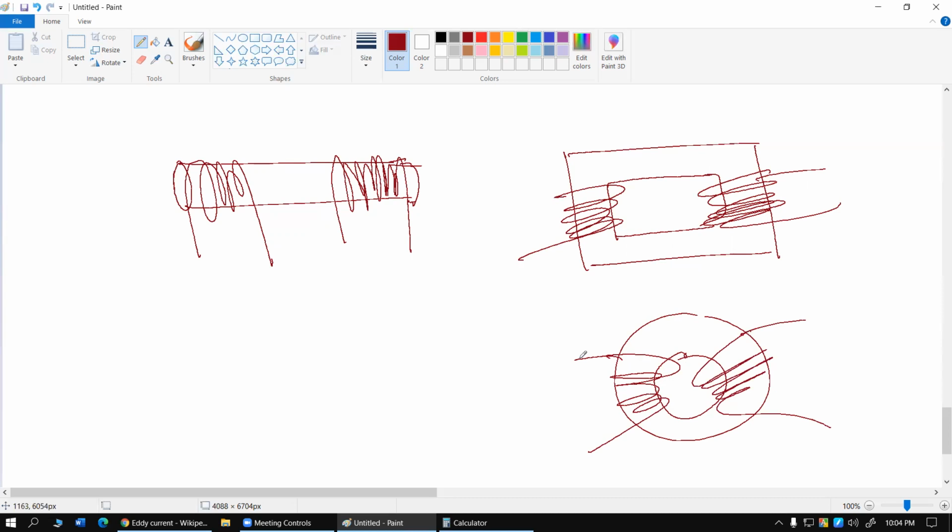For all of these cases, whenever this transformer happens, you have to understand that when the primary coil produces current through the coil, and it is an AC supply importantly, this part of the conductor is subjected to the magnetic field induction more strongly compared to the other parts, which definitely produces a current within the soft iron core. The current that is produced within the soft iron core is basically what the eddy current is.